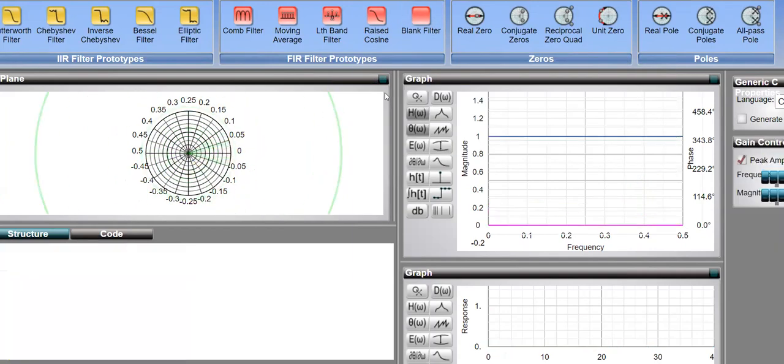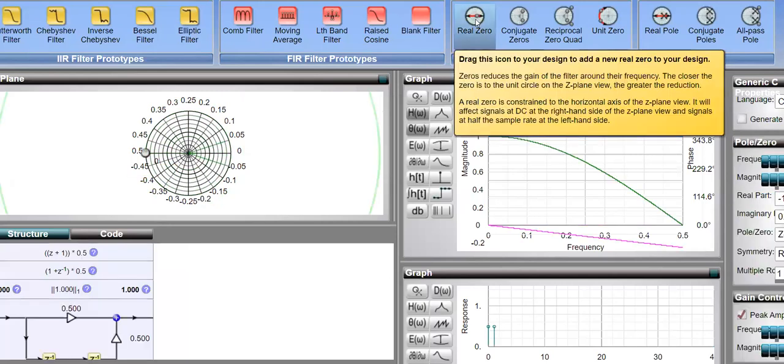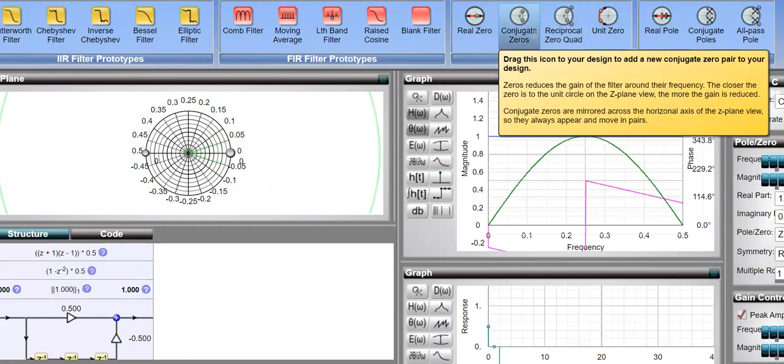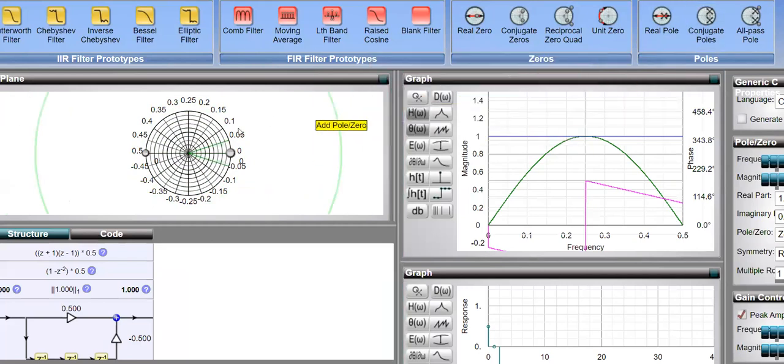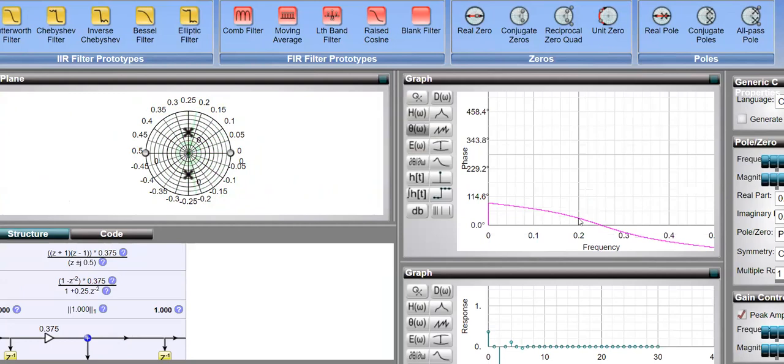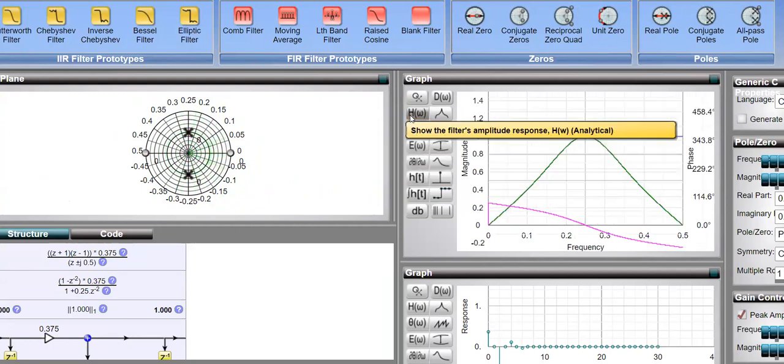Okay, now we can observe the bandpass filter. So this is the fundamental pole locations, zero locations. Now we are putting the pole locations, and that is a complex conjugate. If I only think about the phase, this is again non-linear in pattern.